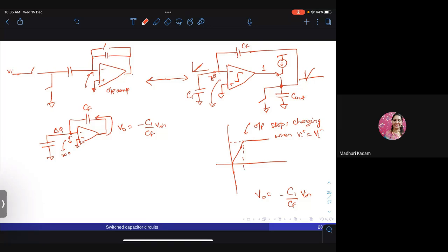Even gain? Gain also? Comparator gain should be high, but you don't need linear gain. High gain is difficult in scaled CMOS only when you're looking for high gain with a high linear range. If you're okay with non-linearity, high gain is very easy. For example, you can use a weak positive feedback in this amplifier to get very high gain. It will be non-linear, but since your output is just going to be 1 or 0, it doesn't matter.